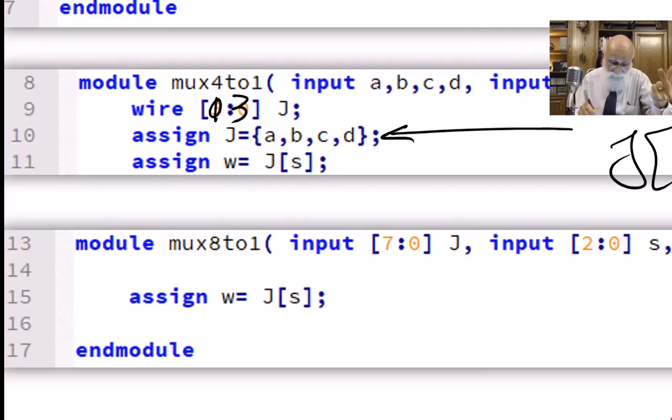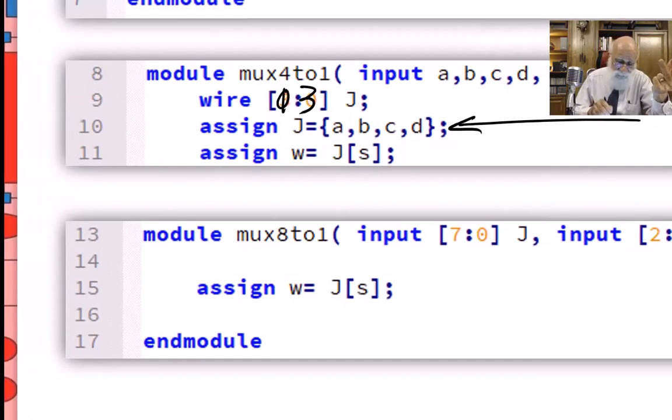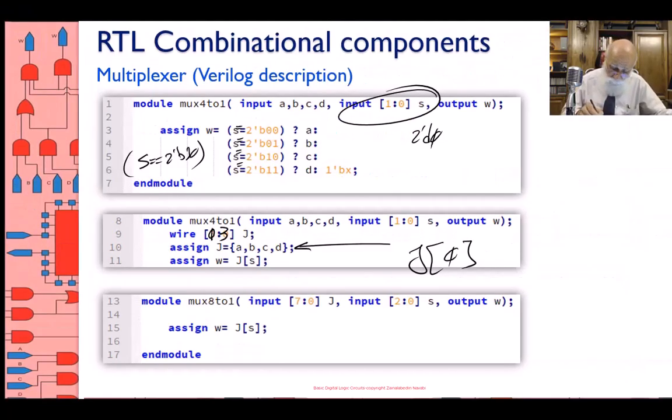Select input 3-bit, and therefore these 3 bits will be selecting one of the J's, and then the J's are the 8 inputs of the multiplexer. So instead of A, B, C, D, E, F, G, H, you have J7, J6, J5, all the way to J0 as the inputs of your 8-to-1 multiplexer.